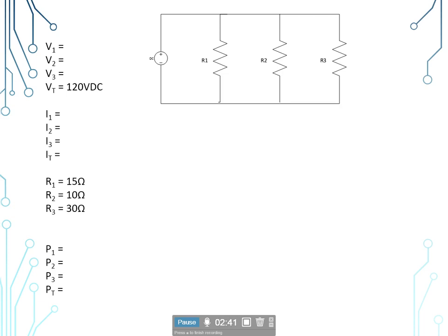We're going to use the reciprocal formula. Now the product over sum is backwards compatible. You can use it where you could use the resistors of equal value, and the reciprocal formula is what we're going to use. It's a 3D fraction. It's the reciprocal of the reciprocals. It doesn't care how many branches you have, you can do it in one calculation, and it is also fully backwards compatible to use on resistors of equal value also.